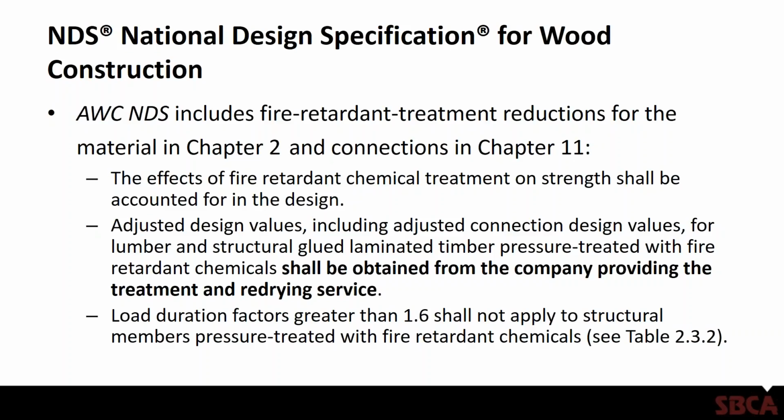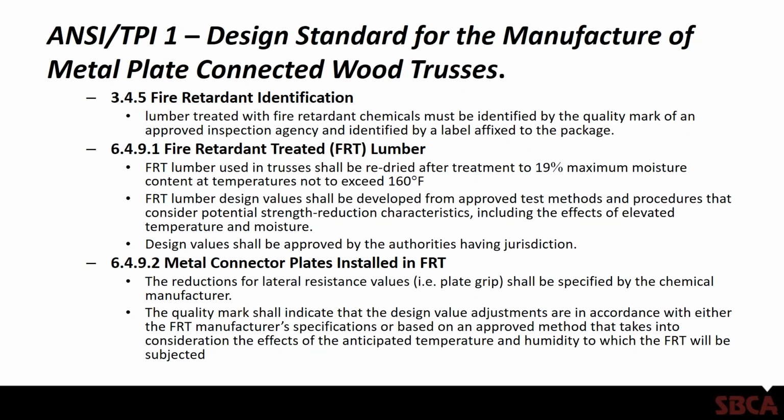redrying service. And with FRT, they can be very brittle, and so fire-retardant treated wood should really never be used in applications where the load duration factor would exceed 1.6. So definitely don't want to use it, say, in impact type of applications or where the material could be subject to impact loads.